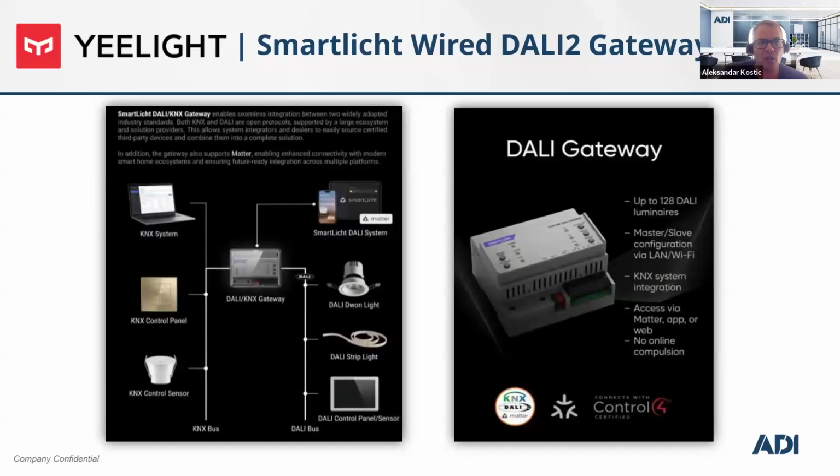There is nothing else to configure there. The DALI gateway itself has its own web interface, so you can log in using its IP address. There you have the option to scan the DALI line to discover all DALI lighting loads, and also to create groups and scenes.